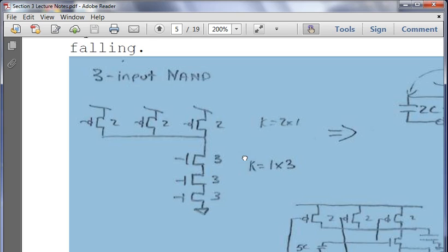If you remember back to the stick diagram, the reason why is now you're going from VDD up to the N diffusion region, and you're going through all 3 transistors. Now we have all these capacitances, these shared and merged and intrusive diffusion capacitances. So now you're dealing with all of that, so now we're multiplying it times 3.